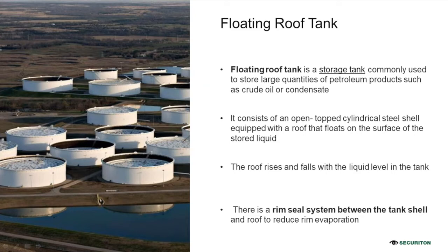When you start to fill in the crude oil, the roof floats, and when the liquids are being taken out, the roof drops down. There is a rim seal around the rim of the surface, which gives friction. That is the major cause of incidents in normal cases of a floating roof tank, which we will look into today.